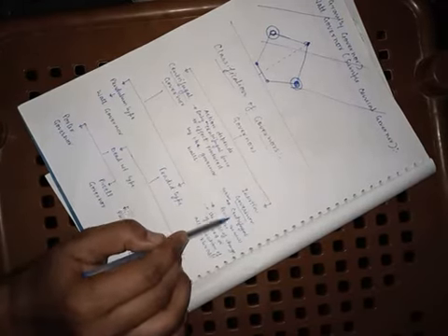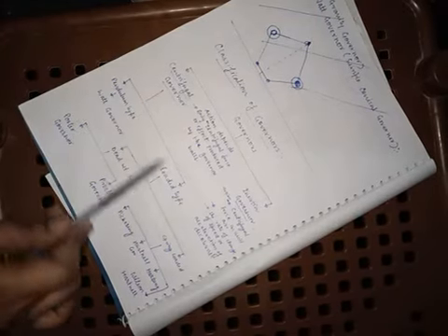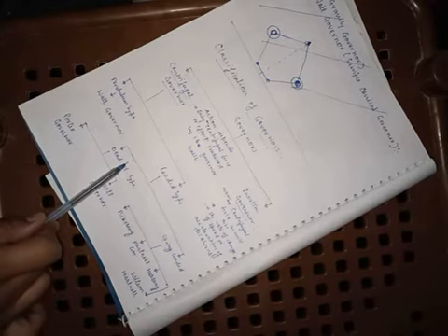Next, centrifugal governors are pendulum type or loaded type. Pendulum type has only the Watt governor. Loaded governors, whether deadweight type or spring loaded, are these and these. So this is how we can classify the governors.